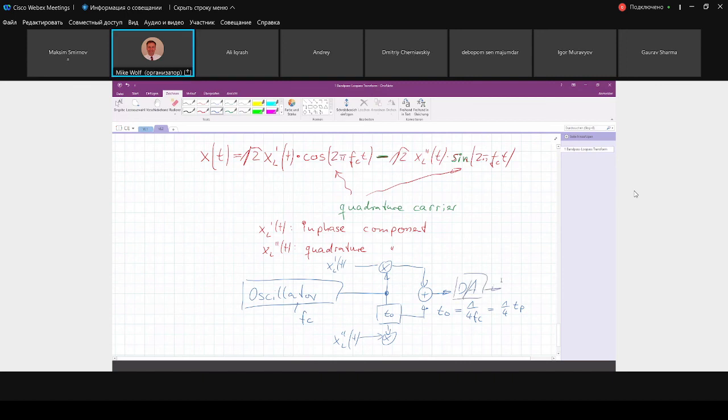And then I do a further upconversion just by multiplying with another harmonic wave. This makes the final shift in the frequency domain, let's say, to 2.4 gigahertz or so. So we first upconvert to, let's say, 200 megahertz, and then to 2.4 gigahertz.